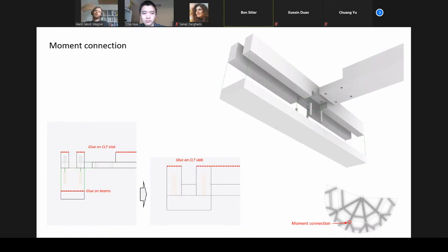Would you have the LVL layer standing or flat? Yeah, so each of these pieces would be an LVL beam, and they would have a minimum of 3 plies. So these would be 45 mm thick as a minimum. And so to chop that down into smaller pieces and then re-glue on site. Wait, are you talking about cross-laminated timber or LVL?